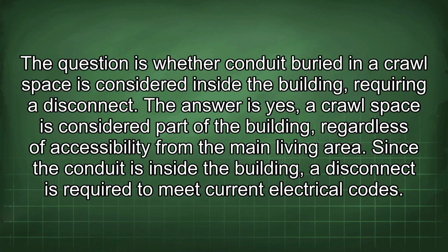The question is whether conduit buried in the crawl space is considered inside the building, requiring a disconnect. The answer is yes, a crawl space is considered part of the building, regardless of accessibility from the main living area. Since the conduit is inside the building, a disconnect is required to meet current electrical codes.